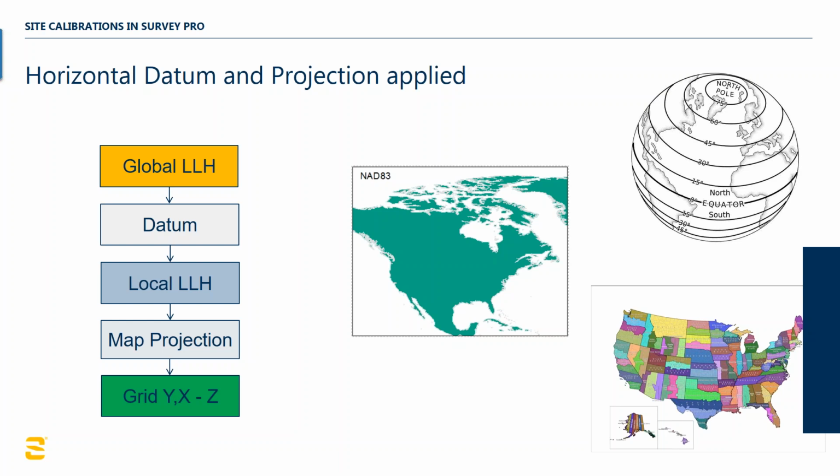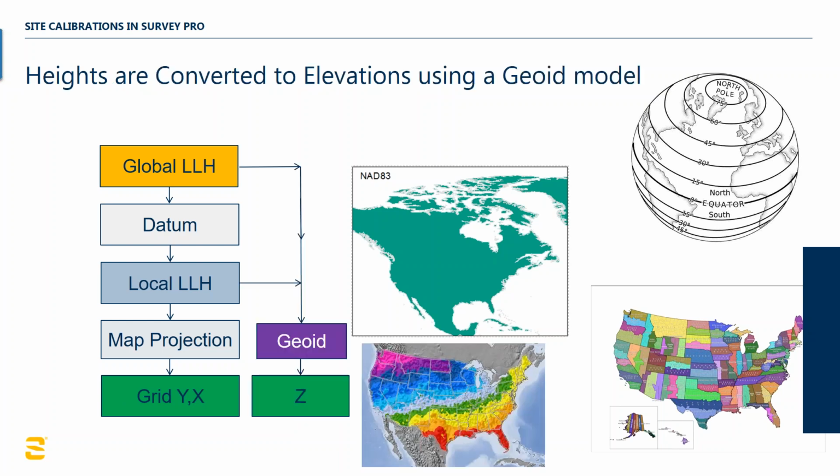If I were to choose one example, you can see Wisconsin has 3 zones. They're Lambert zones. You've got a north, a center, and a south. And that's the way their state plane coordinates are. Generally, state plane systems are developed based on the geography, the shape of the state. So you can automatically know that a state like Tennessee is going to have a Lambert parallel because it's a long, skinny state.